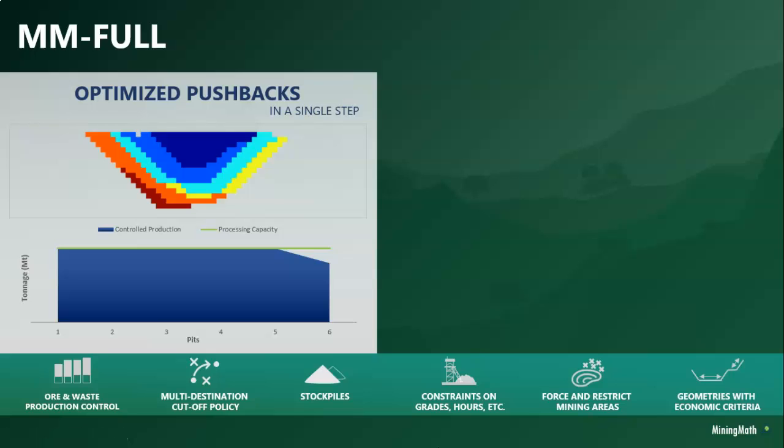And here we can also add variables of minimum bottom width, that is this distance here, based on the size of your equipment, the size that you need to work in this bottom here. And we also can input the minimum mining width, that is the horizontal distance between one cave and another cave. And we can add the minimum rate of advance here.